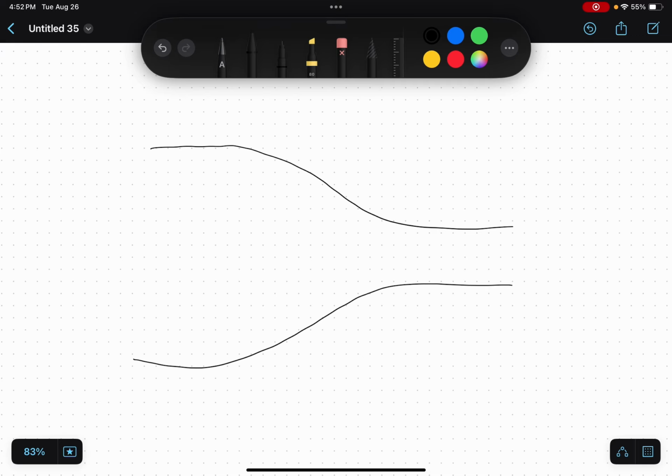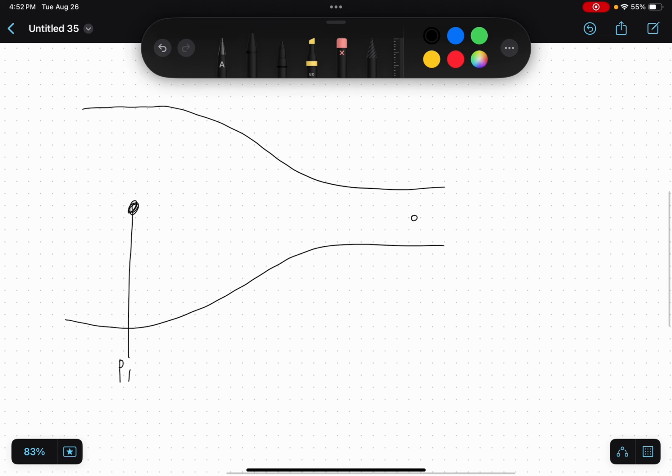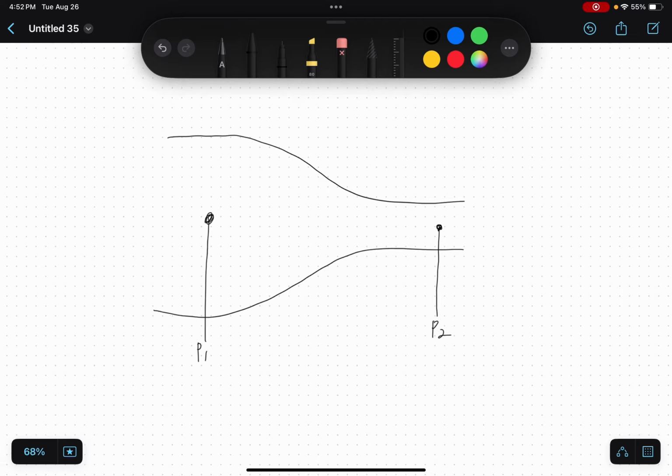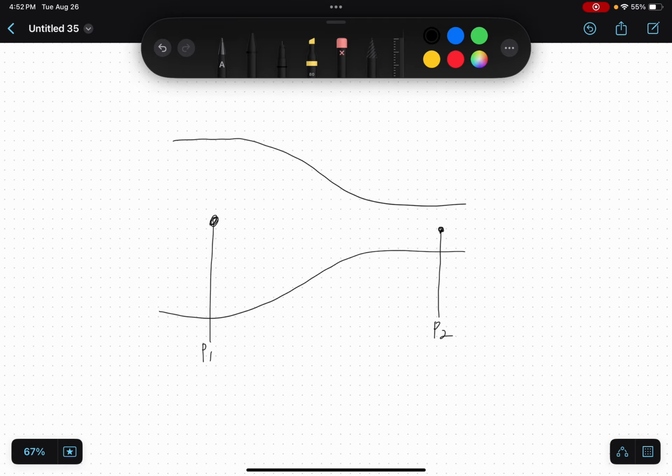So yeah, the big idea is you have a pressure probe right there, P1. You have another pressure probe over here, P2. And based on the difference in these pressures, you can measure flow. Well, okay, first of all, why would the pressures be different? Big picture, mass is conserved, so the velocity here, V1, is less than V2, and V2 is over here.